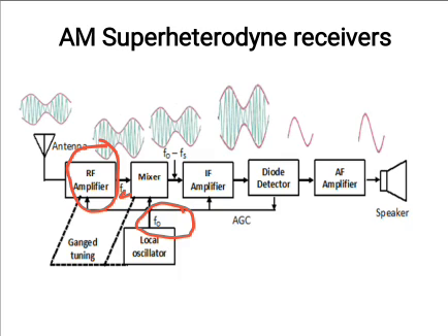The IF signal is amplified with the help of the IF amplifier, which raises its level for the information extraction process. Also, the IF amplifier fulfills most of the gain and bandwidth requirements of the receiver. IF amplifier operations are independent of the frequency at which the receiver is tuned, maintaining the selectivity and sensitivity of the superheterodyne receiver considerably constant throughout the tuning range of the receiver.